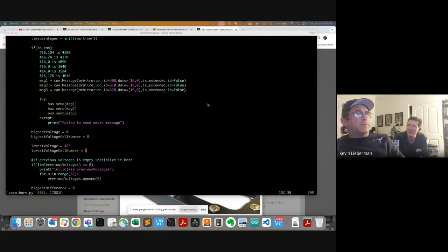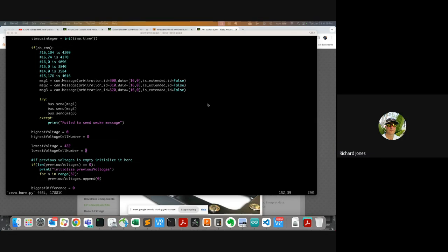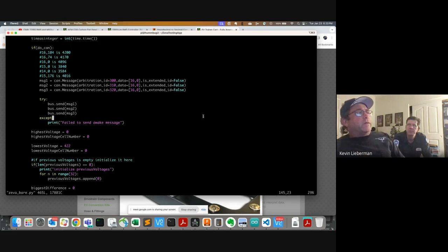So he's made that very easy, but the DBC file represents a lot of time invested to get it right. And there are tools out there to create the DBC file. When you have a description, like say in the back of the dilithium's manual, once someone creates that DBC file once, it can be used in AEM, but it can also be used in any other tool out there that uses this industry standard database that describes CAN messages and the signals within them. Yeah, it's the dictionary that I was talking about before. It's a dictionary of what these signals mean.